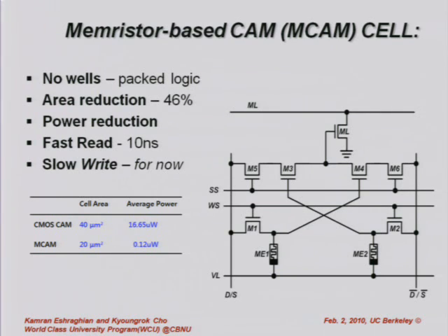we select the word line here. Then transistors M1 and M2 should be on. Then the state of memristors ME1 and ME2 is decided by the data on the bit line. At that time, the VL keeps a low voltage.